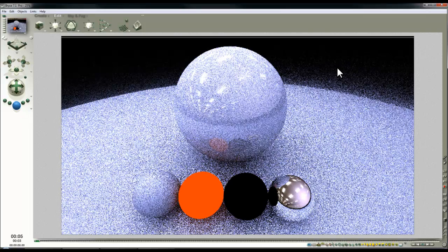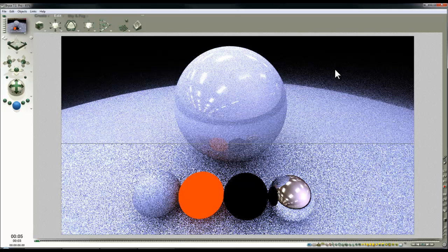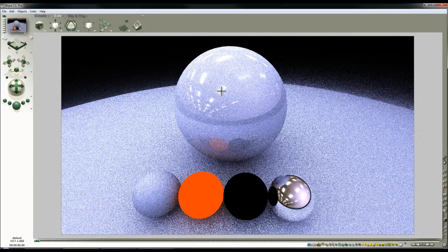So what's happening is the True Ambience, when you're looking at a portion of the ground here which is in default grey, is looking up at the HDRI image, and because the HDRI image is made of high dynamic range components, very very bright and then less bright, more so than you would find in any other environment within Bryce, if it's not high dynamic range, then it might see something that's bright and the next pixel might see something that's dark, and that's where your noise comes from.